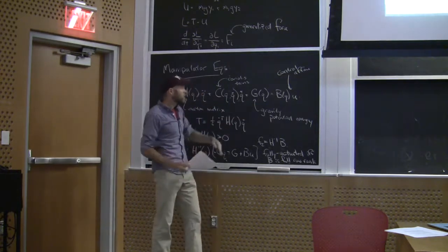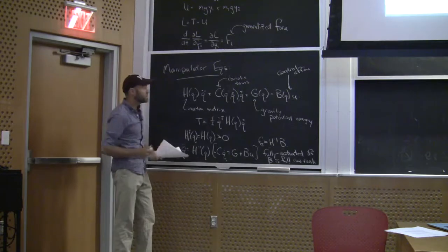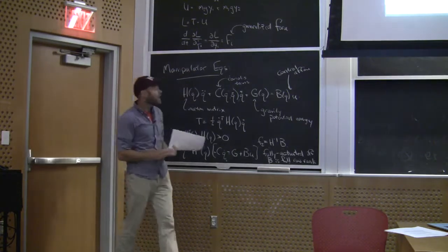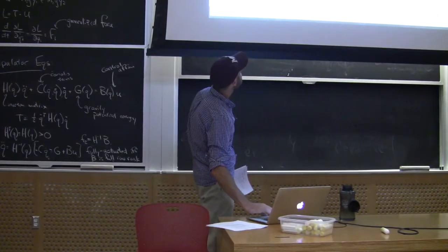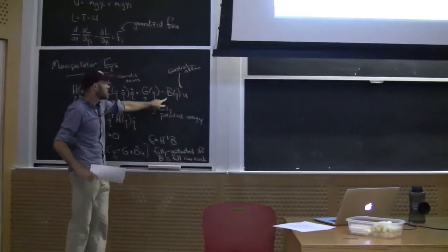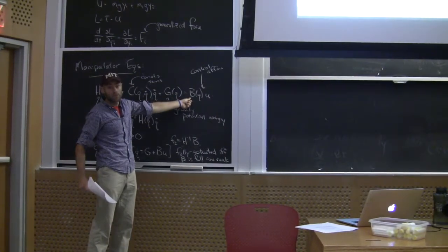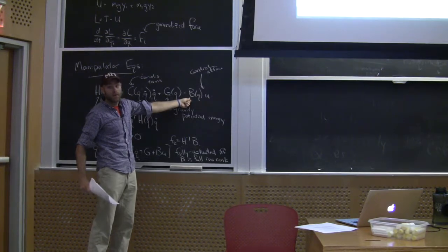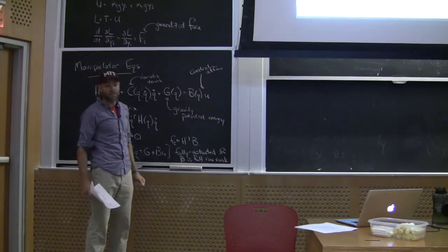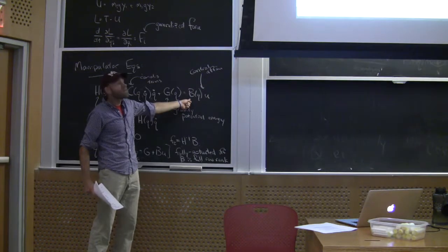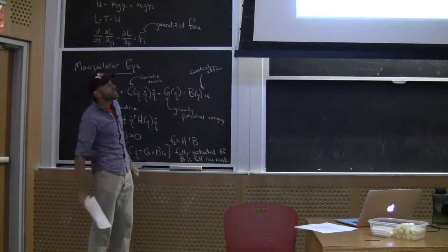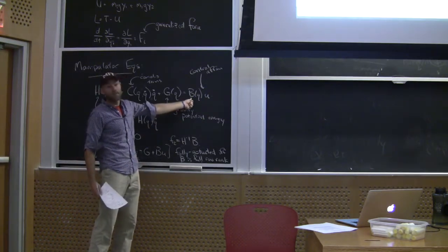Okay, so in my simple double pendulum example, if I have a torque motor here and a torque motor here, tau 1 and tau 2, and I write that in this manipulator form, then B is going to be the 2 by 2 identity matrix. That system has full row rank. It's fully actuated. I can do whatever I want to that system, and we will in just a second. If for some reason we were to leave an actuator off, let's say we've got an actuator in the elbow but not in the shoulder, then suddenly B drops rank, and I've got an underactuated system.